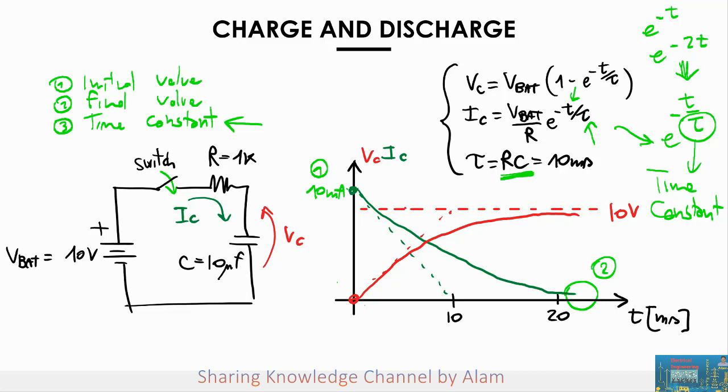Very simple. Here's what you do. You already identified in the graph your starting point and your ending point, the final value. So what you do is draw a line parallel to the time axis that reaches your final point. In this case, the final point is 0, so this line is basically overlapping with the time axis, but it doesn't have to be that case, the final value could be somewhere else.